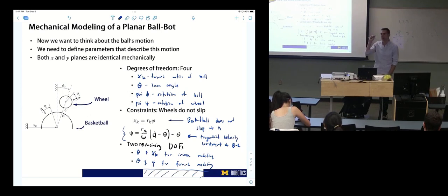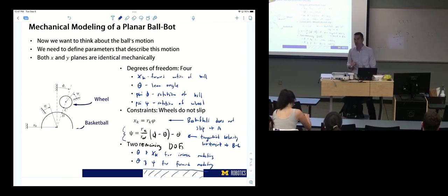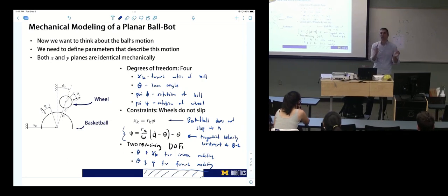So our system has 4 degrees of freedom, reduces to 2. That means in this analysis, we need to have motion profiles for these degrees of freedom. So now we need to create motion. And what we're going to get is the torque required to do that motion. So whatever we give it in terms of these motion profiles, it's going to return to us the torque required to do that. So picking those motion profiles is important because we're benchmarking everything on what we get for this specific motion profile.